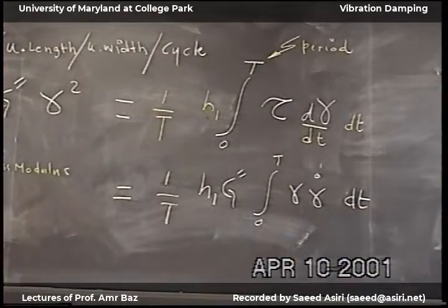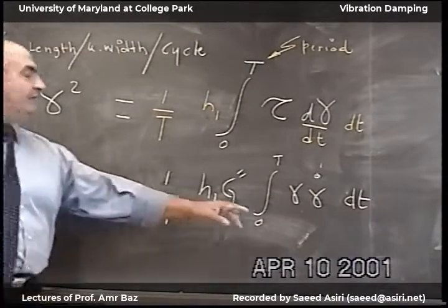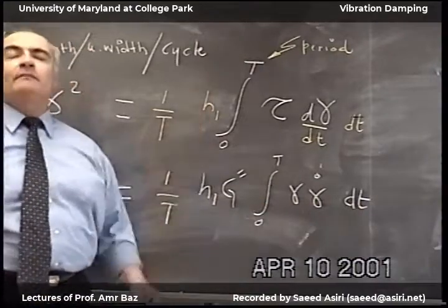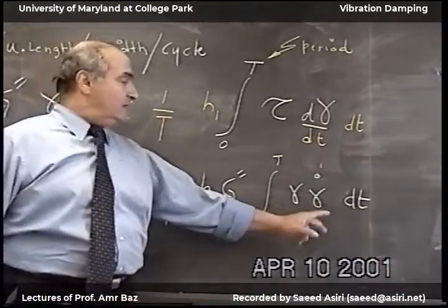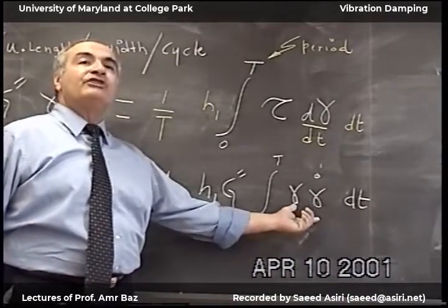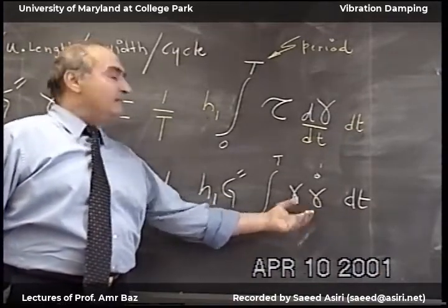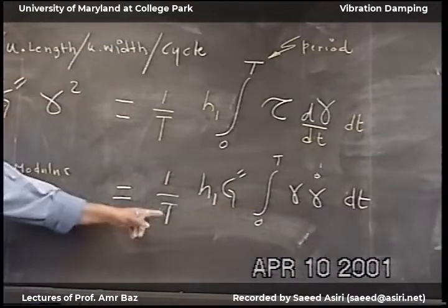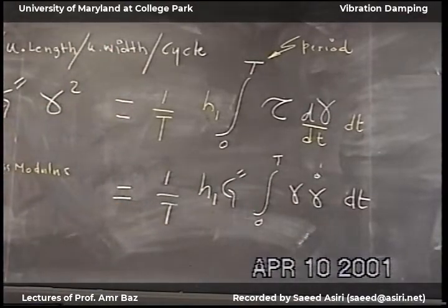And we've done this in the vibration class. If I have stress, if I have viscous damping, and I have displacement, this is sine and cosine, multiply them, integrate, divide by this, so it will become this term. So the final result of all this is this side. Now,